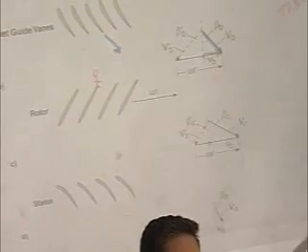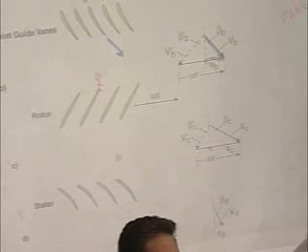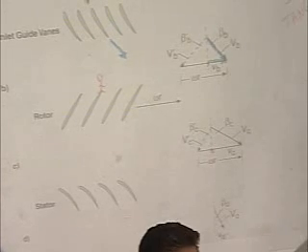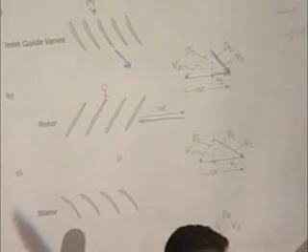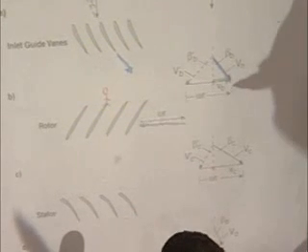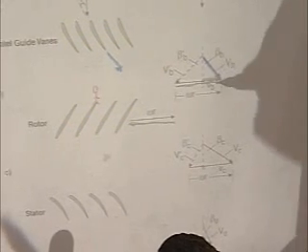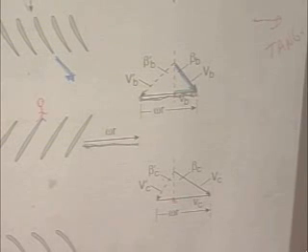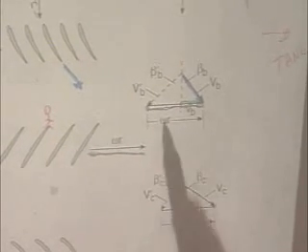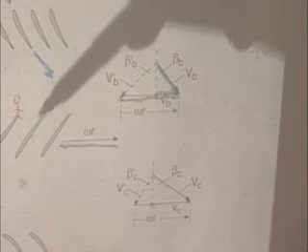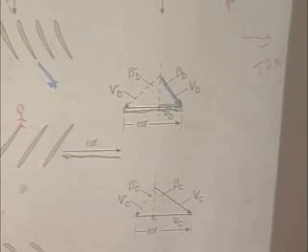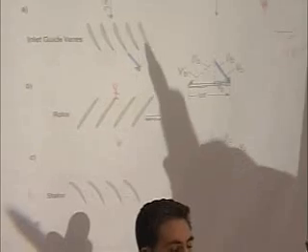Now, this does not look good, right, to have flow coming into this blade, and it's almost perpendicular to it. When you transform to the reference frame of this rotor, you'll see that it lines up with it beautifully. The way you transform to the reference frame of this rotor is you take this velocity and you now add, depending on your frame of reference, or subtract, the speed of the reference frame. Unclear, my apologies. If you are in this reference frame and you want to transform it to the reference frame of someone sitting on these blades, you need to take account of the speed of this reference frame with respect to that one.